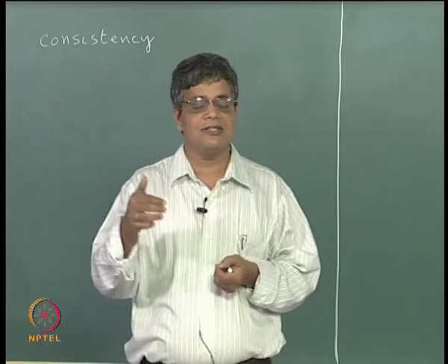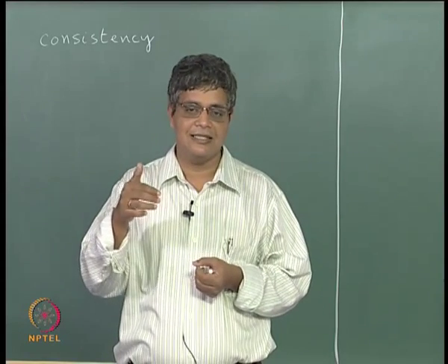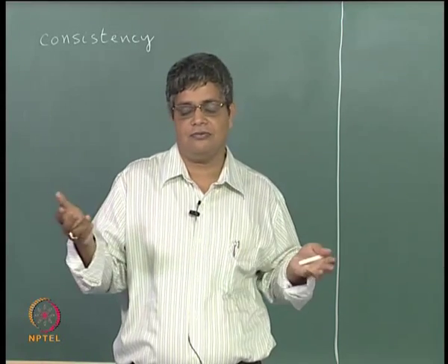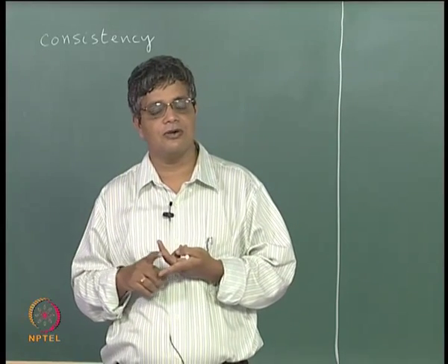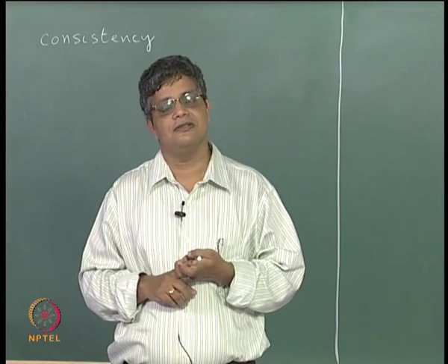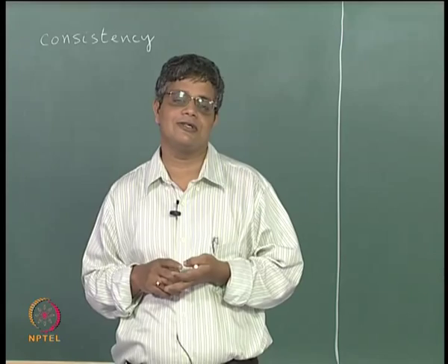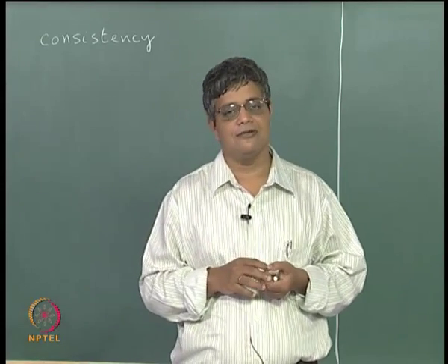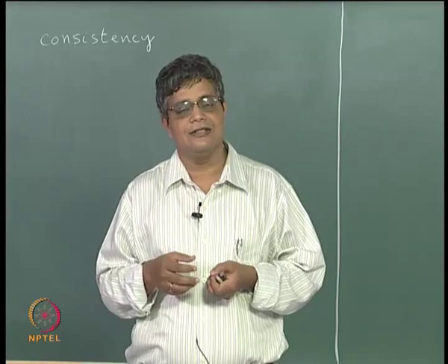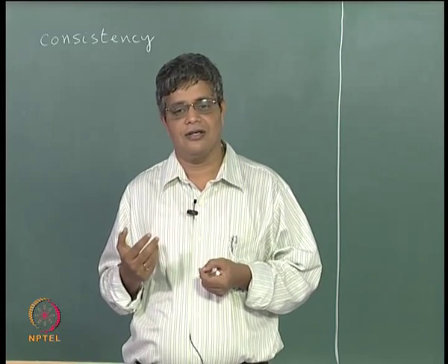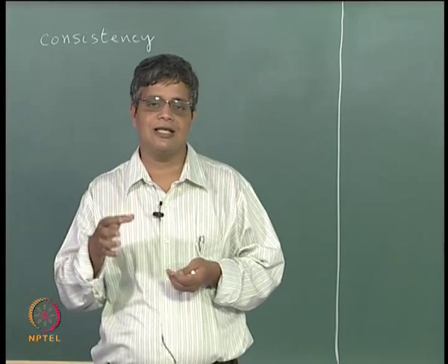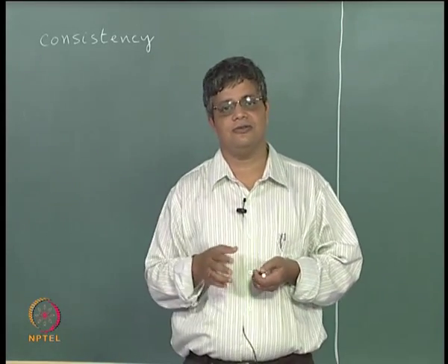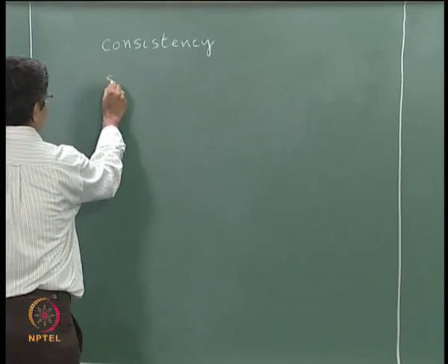So this brings us to the second condition, stability. Does the discretized equation have the property of stability, whereby errors that are introduced from whatever reason, from finite precision arithmetic or rounding off errors, or from boundary conditions or from truncation errors, errors related to discretization, or even simple typographical mistakes, such errors, do they get amplified, or is the scheme stable in such a way that those errors will be suppressed and attenuated, and finally as time progresses we get to a stable solution? So the second question therefore is stability.